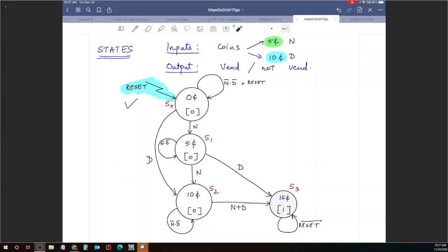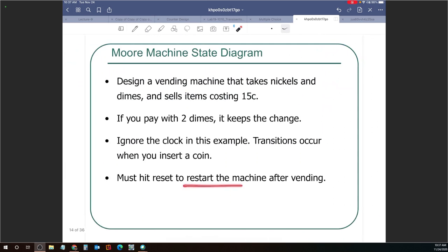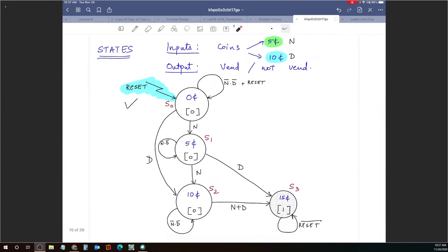So we wrote that assumption just so that we have a very simple case to deal with. However, if you have those kinds of realistic situations come into your finite state machine design, then your design gets a little bit more complicated, but that's what happens in real vending machines. This is just an example in which we are dealing with a limited number of states, only 4 states here. So a user would have to literally press the reset button to come back over here to state 0.